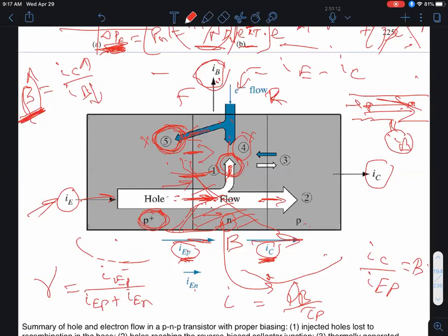And that's why I got an expression for the emitter current. Remember that? Well, we called that the diode current, but here that would be the emitter current. So I have a steady state distribution of excess carriers that are lost at a generation recombination rate of tau P, and therefore you have to replenish them at the same rate. So that's my expression for the current, right? That was a charge control way of calculating current in a diode.